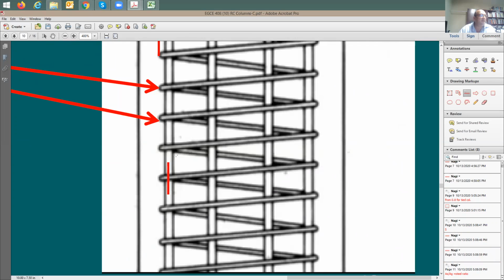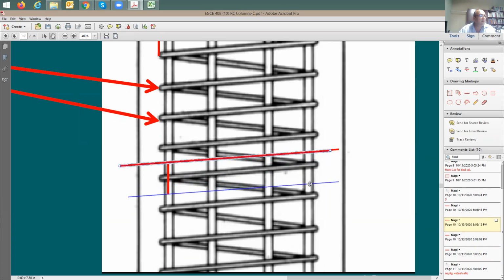Now, try to cut this. Take a slice of this column. I'm going to cut it this way and also cut it this way. Okay, take it this way. Find out the volume of this steel rebar, for the tie only, not the vertical rebars, divided by this volume that you just cut through. So how much is this volume? How can you do the analysis for this volume?